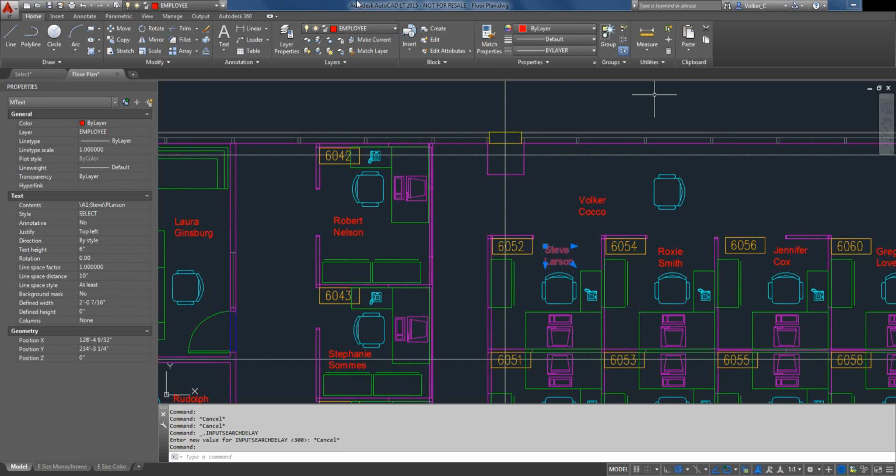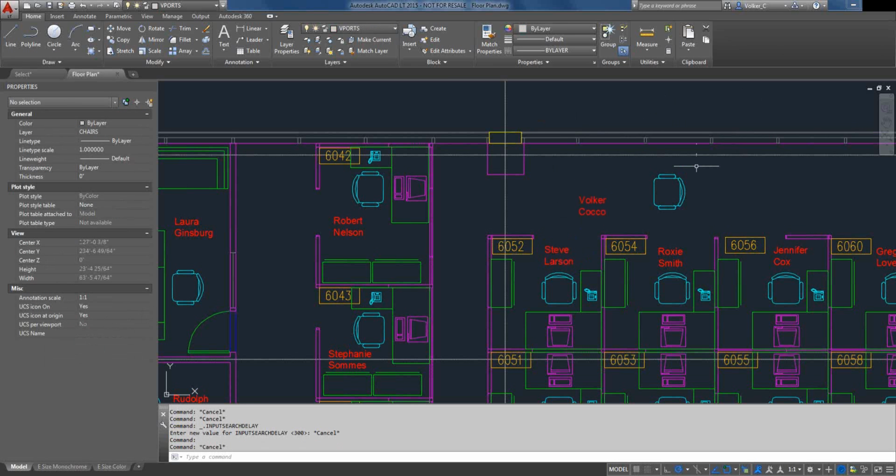Other than that, in AutoCAD LT and even full AutoCAD, the easiest way is to use XOPEN, and I prefer that over REFEDIT. The key word about reference files is that they are reference files, so they keep you from accidentally selecting stuff in them. There's a reason they're locked out from the selection steps.